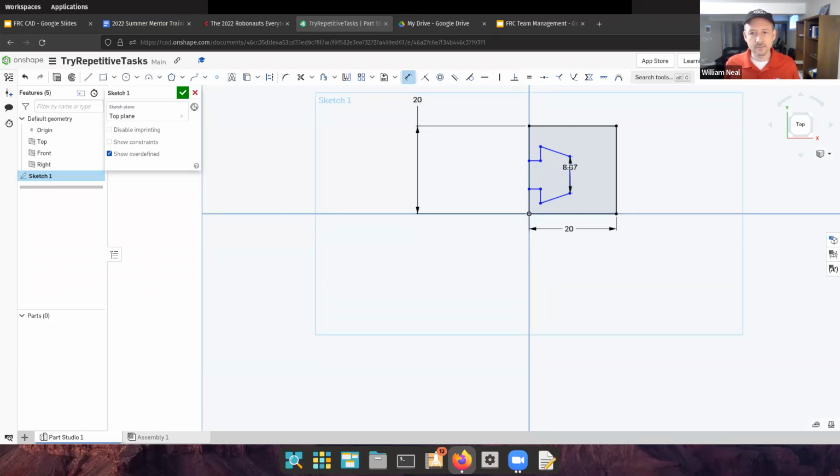Let's say that this one is going to be 5 millimeters. There we are. And then how far above this line is this point here? Let's just guess. I'll take these two features here and click them. I clicked a point and a line, and I can specify the vertical distance between them. Let's say 6 millimeters. There we are.